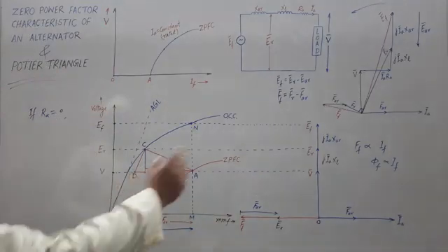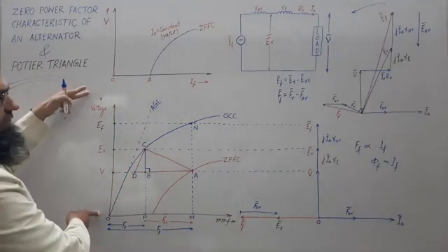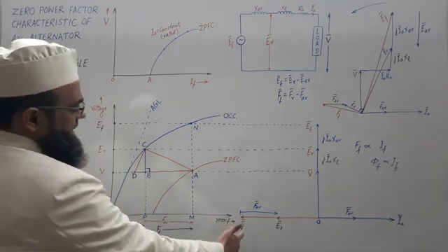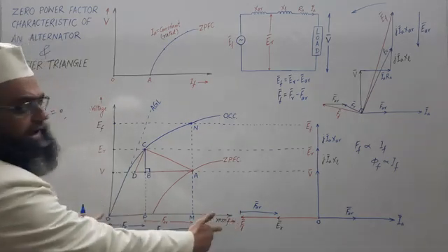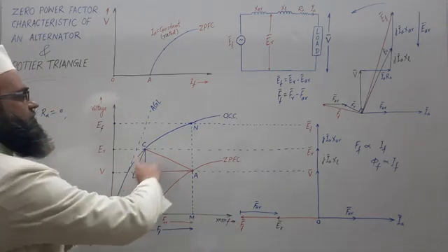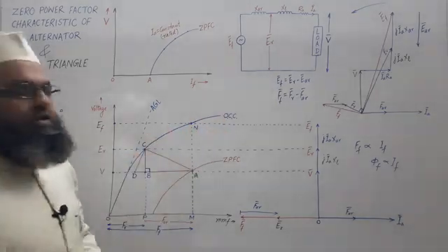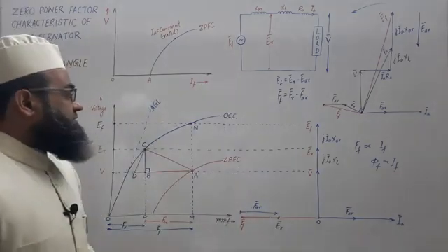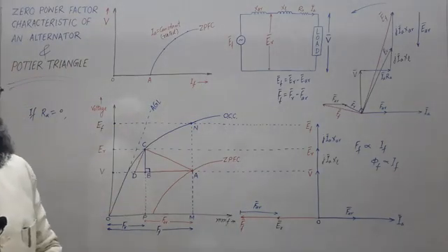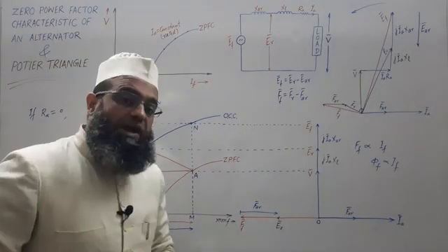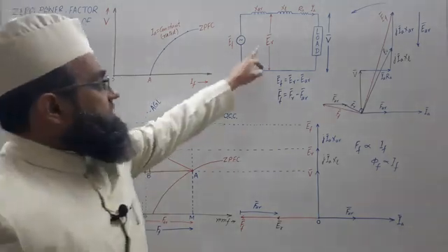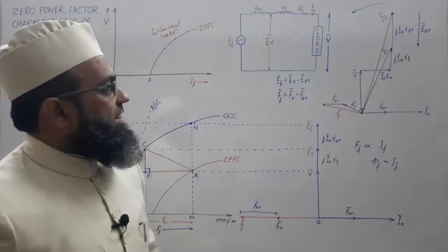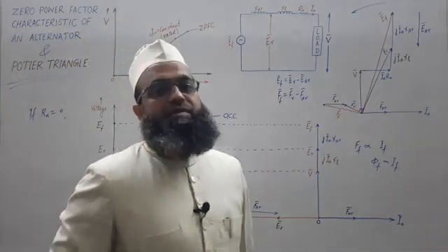So taking terminal voltage on one side against field MMF or field current, we get the nature of the OCC like this. We are going to have one more assumption that this OCC gives the exact relation between the magnitude of ER against FR, the resultant MMF.